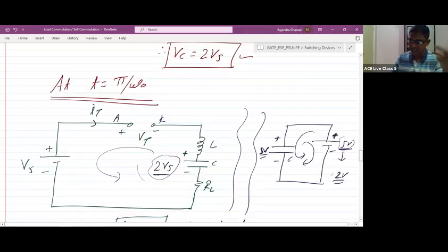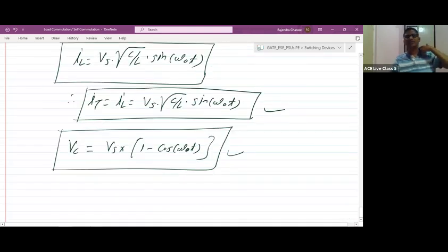So again, the same discussion we can do. For low value of REL, we need to connect it in series. For high value of REL, we need to connect it in parallel with the capacitor. But generally this circuit is not preferred because we are having the voltage commutation and current commutation circuits. Those are the most popular circuits. This circuit has the drawback that it is only for resistive type of load. That's why we are not generally using these circuits.